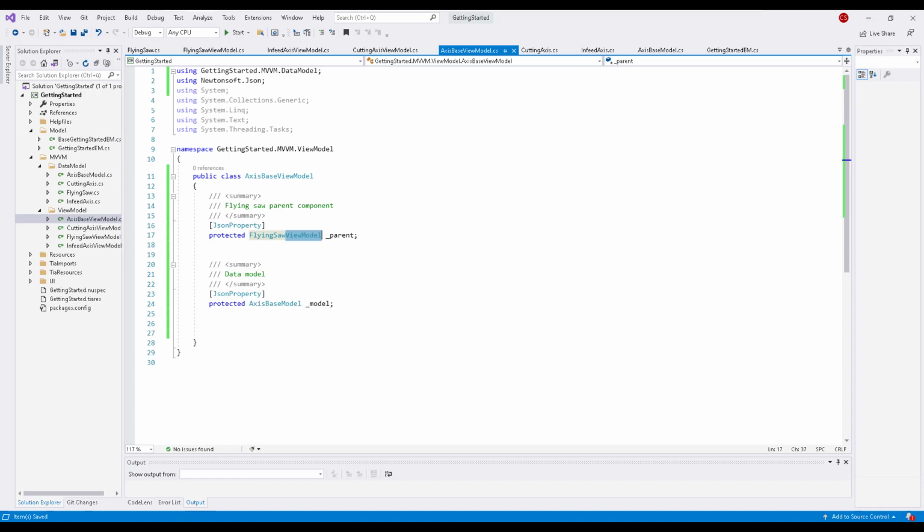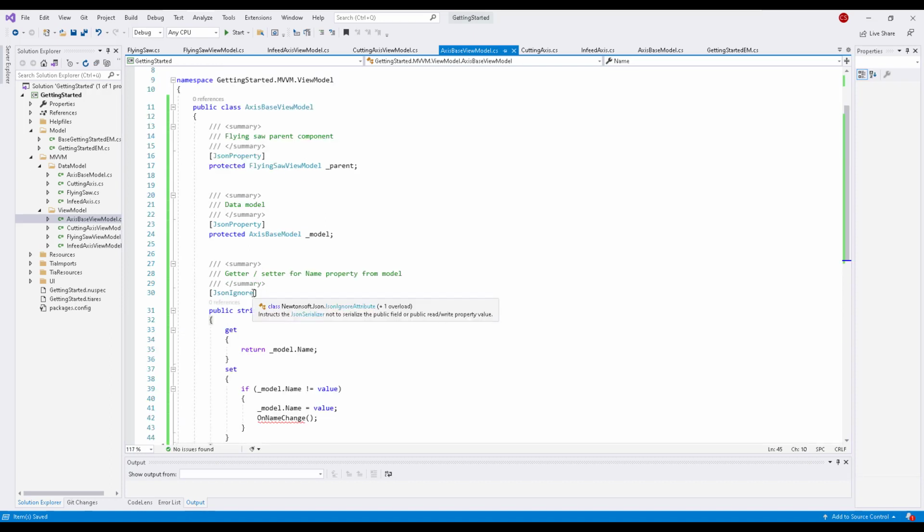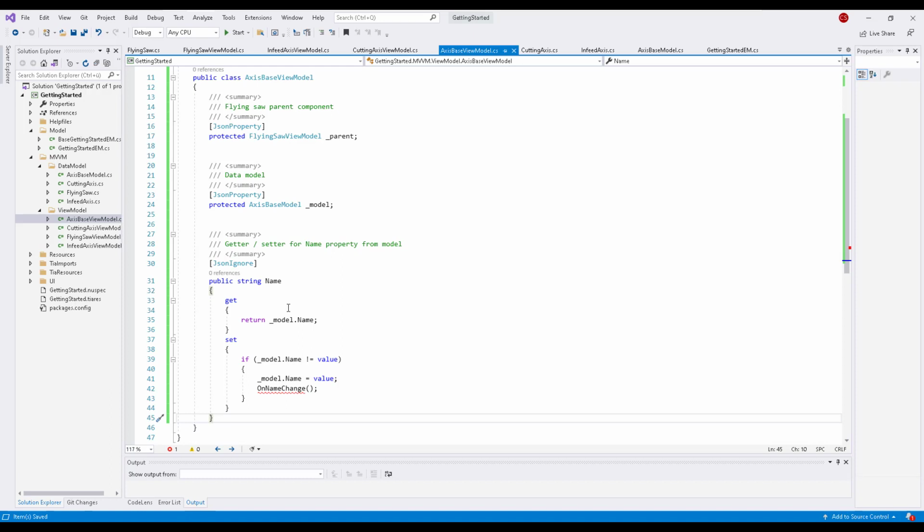And now we get to the point where we are going to access the properties of our model. So what we do for that is normally in the modules for the modular application creator, we create such a getter and a setter for those properties. So basically, this has to be done for each property that is part of the model.